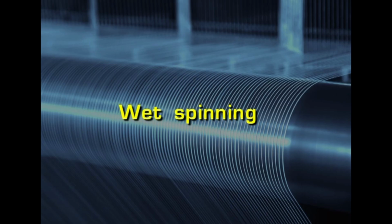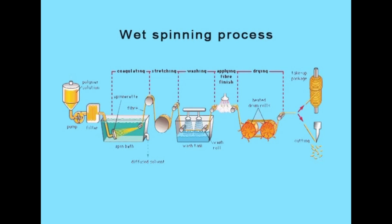The third method of chemical spinning is wet spinning. When the polymer is not in a stage of melting or dissolving in a volatile solvent, then a non-volatile solvent is employed. Since a non-volatile solvent is used, we cannot evaporate it, and so a chemical bath is required in order to coagulate the polymer, so that it comes out in the form of a thin filament. So it requires the chemical bath for these non-volatile solvents.